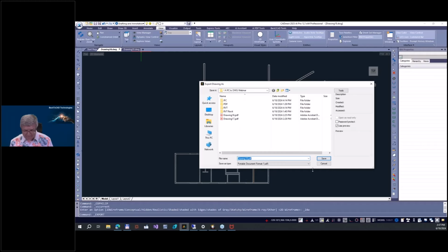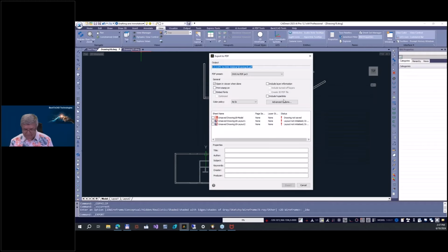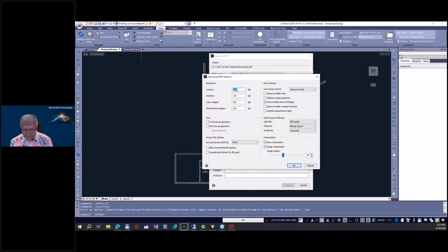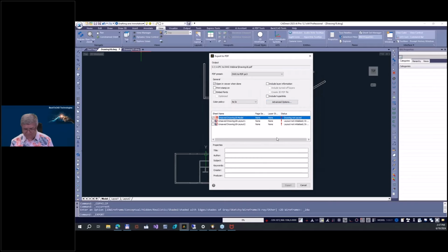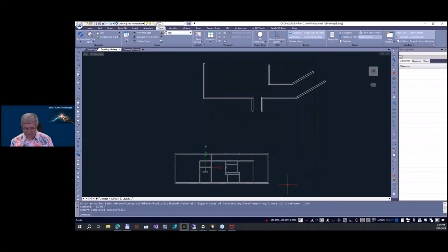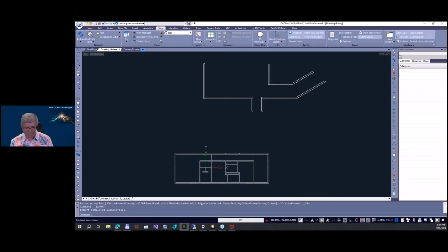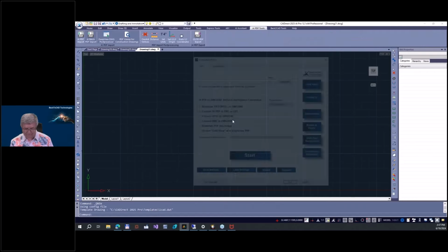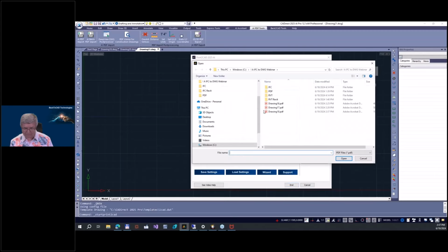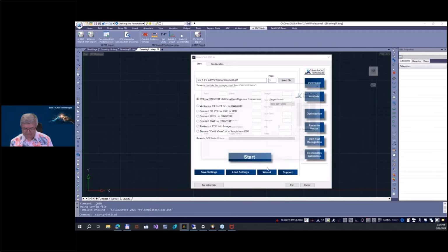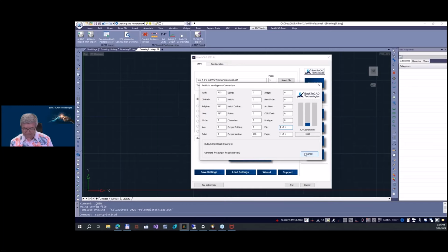PDF. Let me do 18. Okay, and here it's very important that you put here maximum 999 dpi. Very important that you make this in very good accuracy. Okay, that is the drawing, and now we can go here and put it flat here in our A tools, import, and our BackToCAD importer. Take the 18, start, and we'll import it.